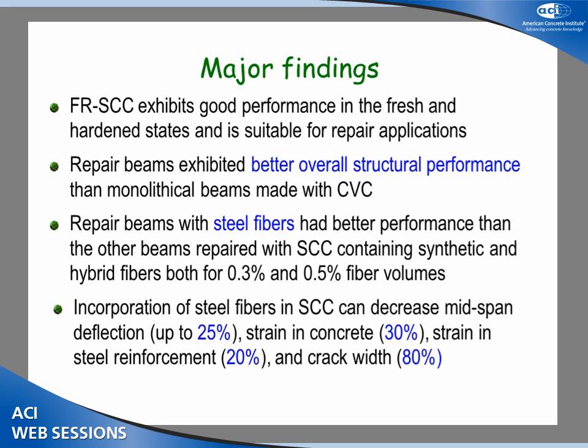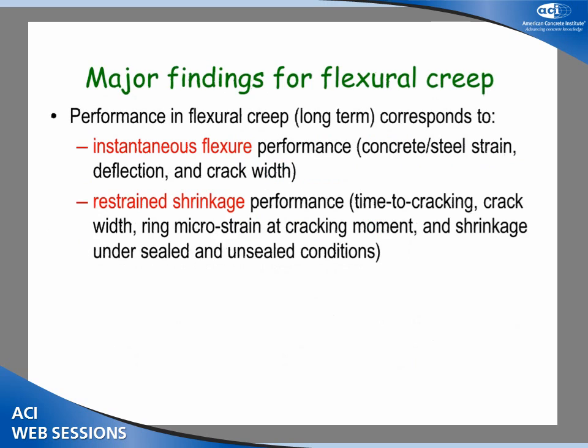0.3 to 0.5%, still getting self-consolidation properties. And I must say also, when you have a 5-inch repair zone and you are placing concrete, you get alignment of the fibers in that. And that's really very, very important to improve the performance of the concrete. The incorporation of the steel fibers can decrease mid-span deflection up to 25%, the strain in the concrete up to 30%, and the crack width up to 80%, which is very, very significant.